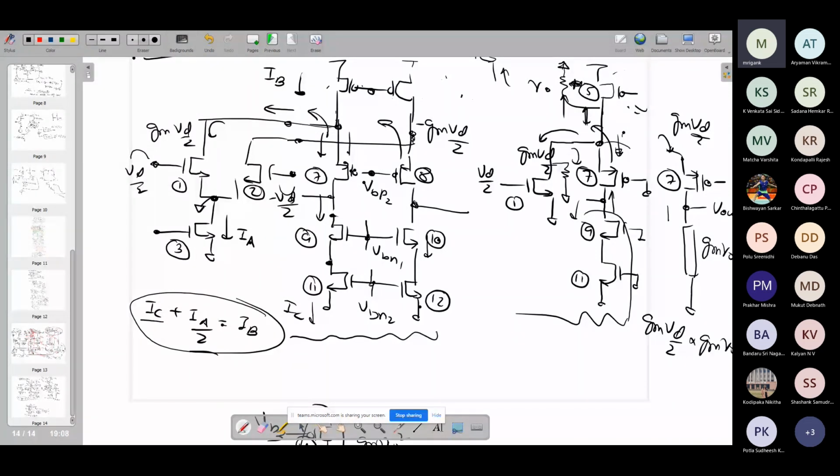So for a single-ended output, what I need to do is, right now what is happening in this fully differential mode, in the stack, both the branches are getting similar small signal current. Whatever small signal current is provided by the input branch, it is getting driven into, or folded into, the two vertical branches by a similar amount. Whatever is the small signal current produced by M1, M2, it goes into these two vertical branches. There is no doubt in that. This is coming from our analysis. This is clear.